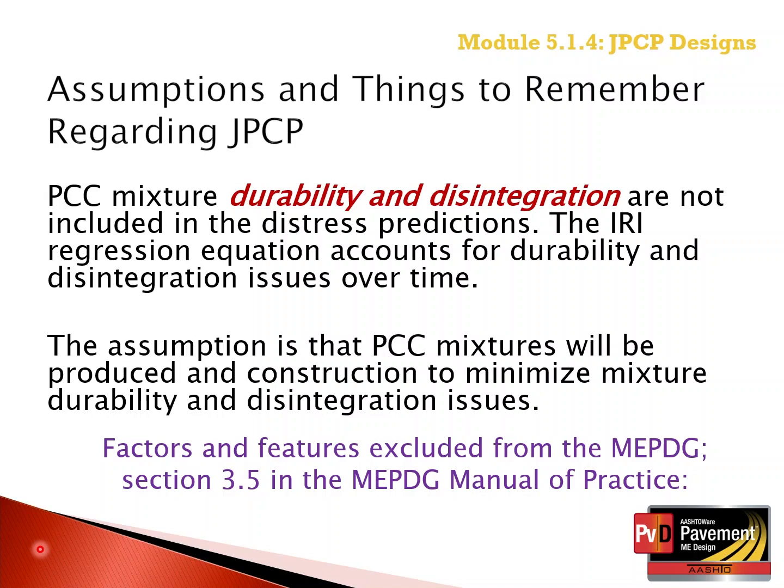Spalling along the transverse joints is predicted by the software. But in those predictions, it is assumed that the PCC mixtures are being designed, produced, and placed to meet standard minimum material specification requirements of the agency, such that D-cracking and other such types of material-related distresses do not occur or will be minimized.